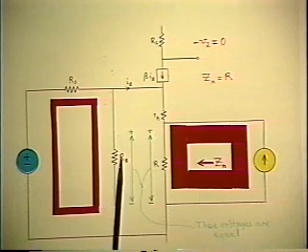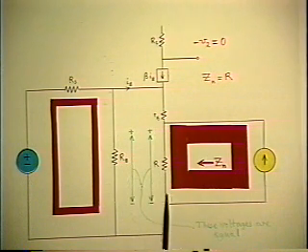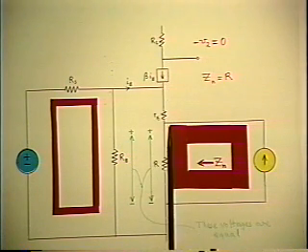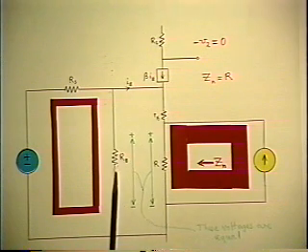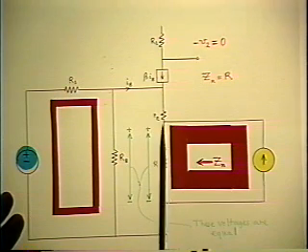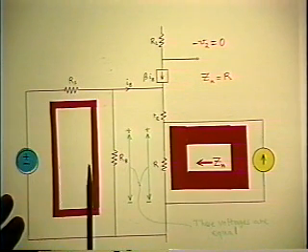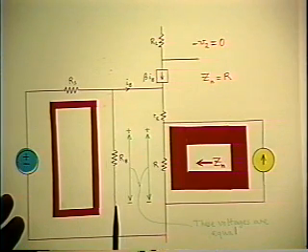In other words, we set up the condition that the voltage drops across RB and R are equal. And this illustrates perhaps even more clearly why it's only the null that you need. Because implicitly, to get a null, the voltage across RB must have the same value as the voltage across R, because that's how you get the null. And the value of V1 necessary to get it is the value of V1 necessary to give that voltage across RB.